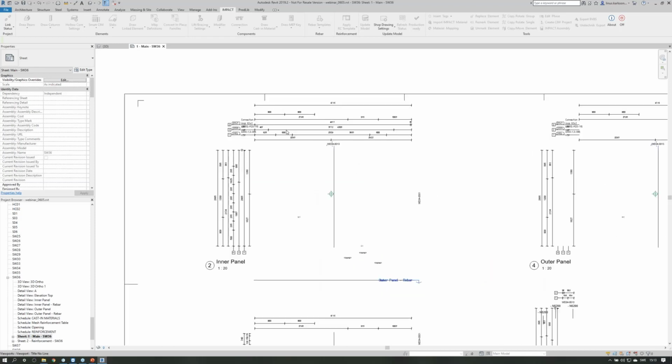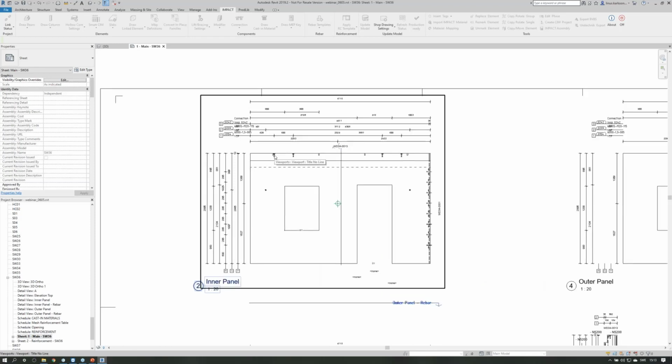But we see here that stuff is dimensioned, so you see the custom materials. Now the description is a little bit long, so here I could just go into this family tag and lengthen it a little bit so that all my annotations fit on one row, so it looks better here. But yeah, everything that I want to get dimensioned is dimensioned. I got the end caps description here.